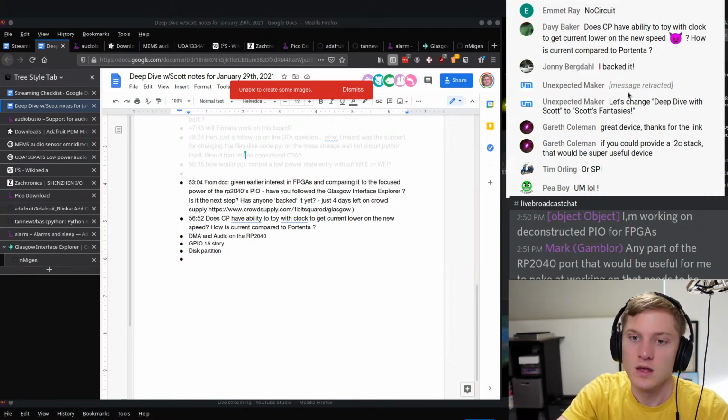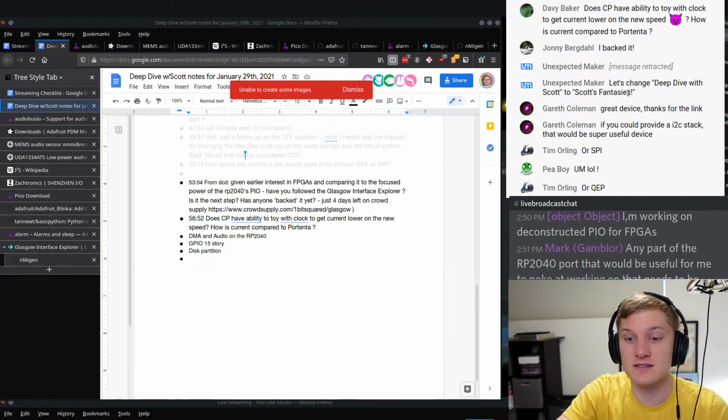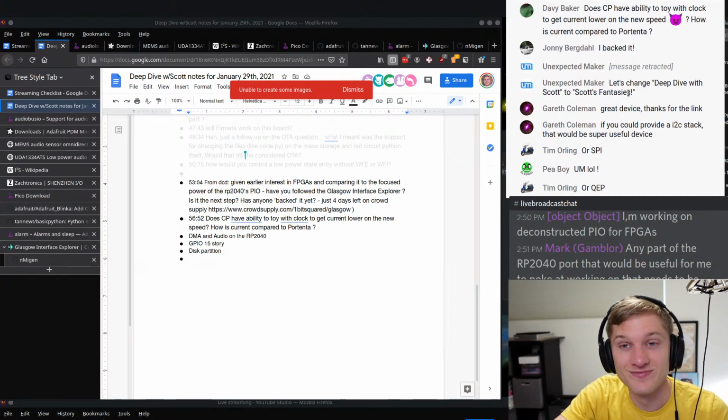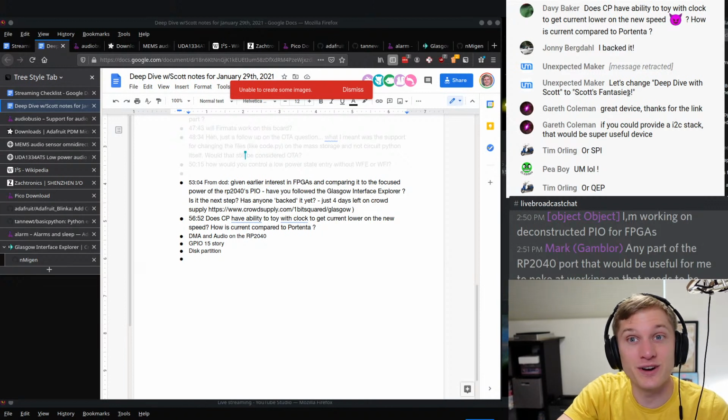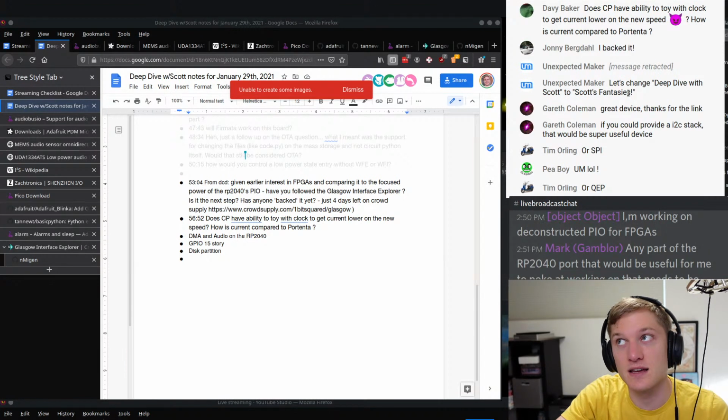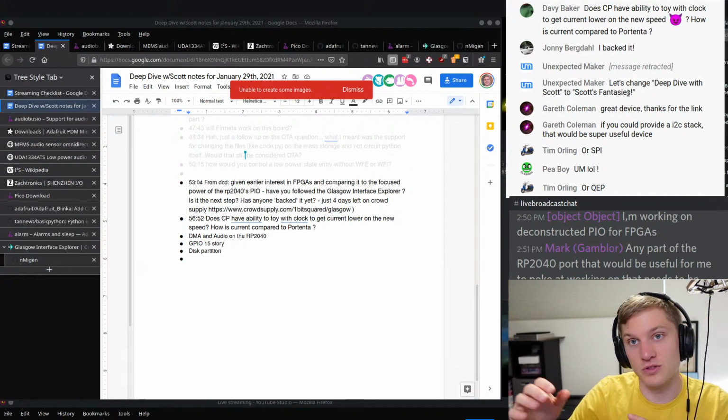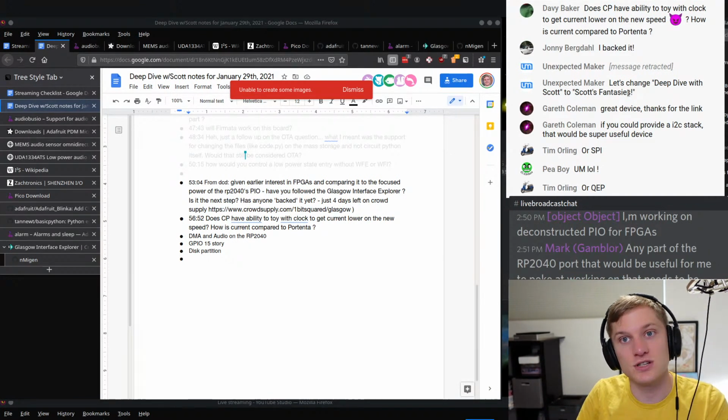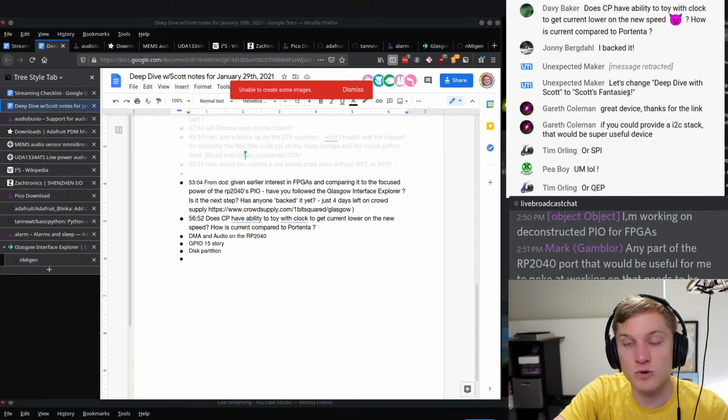Another way to think about the comparison between MicroPython and CircuitPython is that MicroPython's designed if you've read the datasheet, and CircuitPython's designed so you don't have to read the datasheet. The consequence is that the weird parts of the datasheet you may not be able to do through CircuitPython, where you could potentially do them through MicroPython.